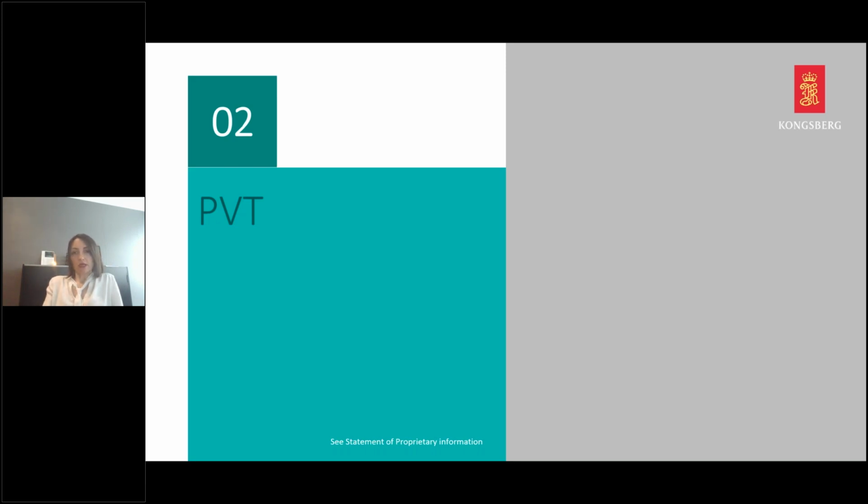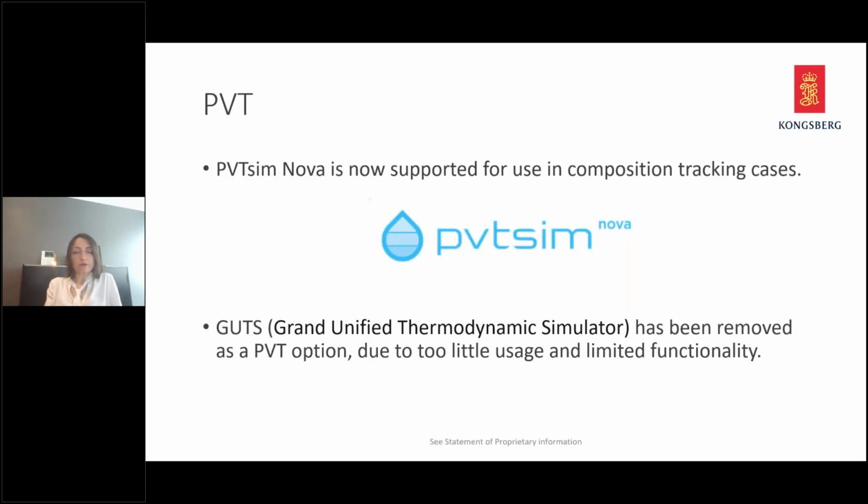Regarding PVT now, we have the possibility to use PVTSim in LedaFlow. PVTSim Nova is supported for use in composition tracking cases. This means that composition tracking is no longer restricted to the use of Multiflash, as long as you have an active license of PVTSim, of course.